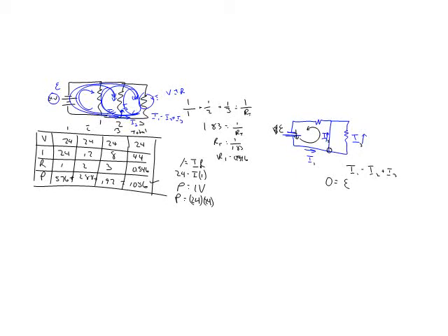And right here, this is still I1, by the way. I2 is anything on this line, I1 is anything on this line. So this would be I1, let's call this R1. Since the current is moving this way, and I'm moving in the same direction across this resistor with my loop, they're in the same direction, so we're going to have negative I1. So this will be minus I1 R1. So there's one loop. Let's do another loop.